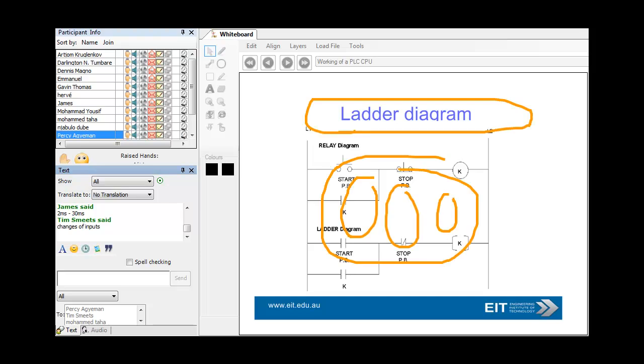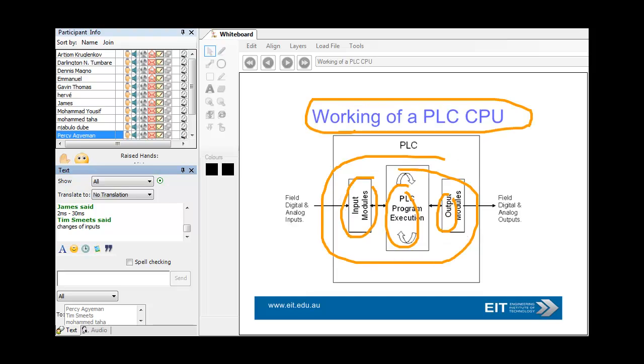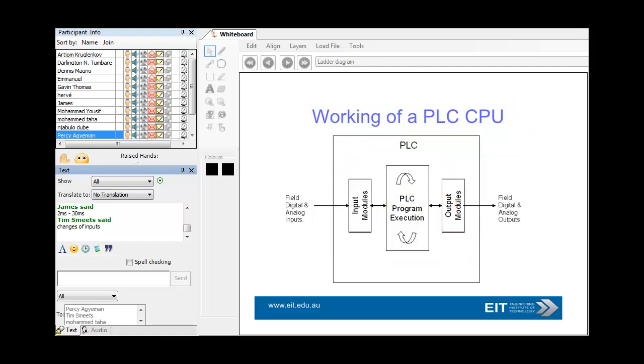There are a few other tasks here as well, which we haven't really spoken about, which can confuse things and be a little bit of a challenge. Sometimes you have what they call asynchronous communications. In other words, you're bringing in values from other I/O racks, and they may arrive at different times during the scan, so that may also cause a bit of issues. But most of the time, it's pretty quick communication.